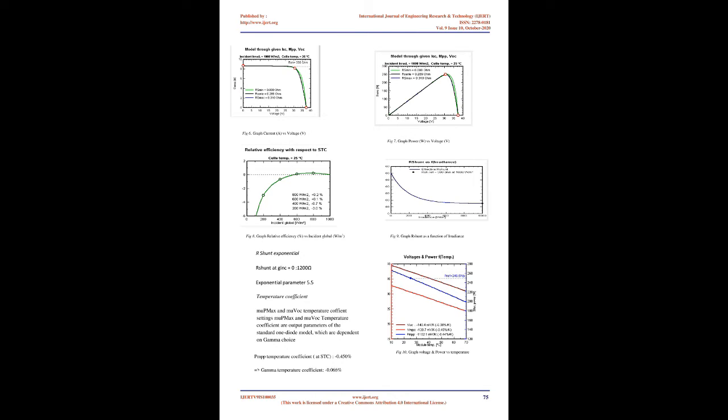is generated. Meteo database. Since we have selected the site we have to enter the geographical data of the particular location. There is a feature called interactive map where we can select the geographic location of the site. The latitude of the site is 28.2900 north and longitude 74.2343 east. Altitude 249 above sea level.